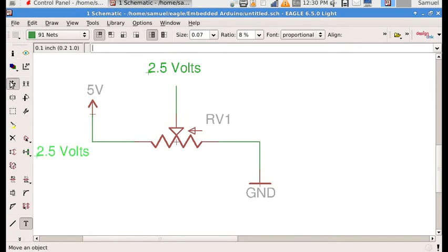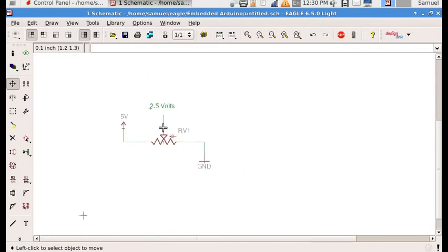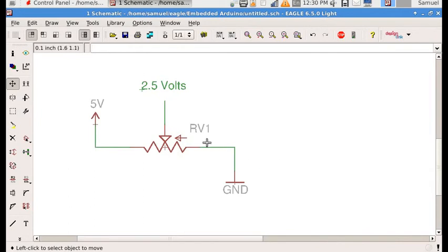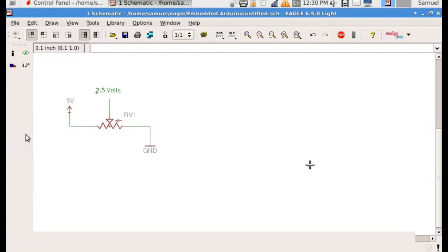And you can go through all the math and tell, if this arrow is between 5 and half, what the voltage will be. But basically when it moves around, it changes the voltage. That's pretty simple. It just divides the voltage between ground and 5 volts. So a theory of pull-up resistors would be if we go get a resistor here.